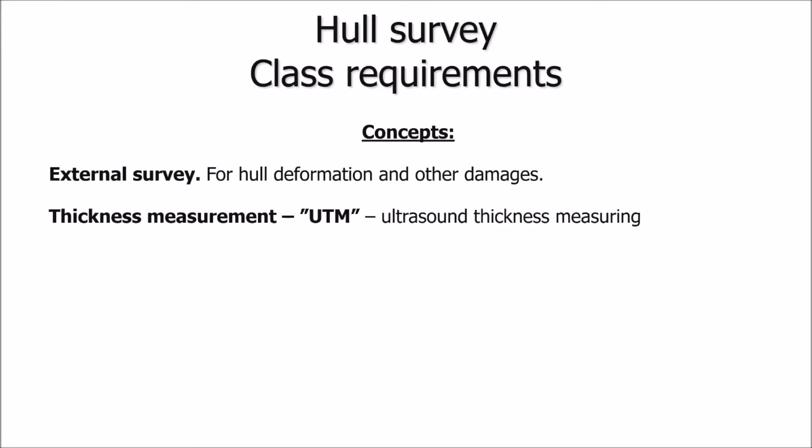And we're going to mention also thickness measurement a little more, UTM, ultrasound thickness measuring, UTM teams of 2 persons usually. We're going to talk about CAP, Condition Assessment Program, which is a voluntary program for assessing the condition of hull, and for some class societies also regarding machinery.